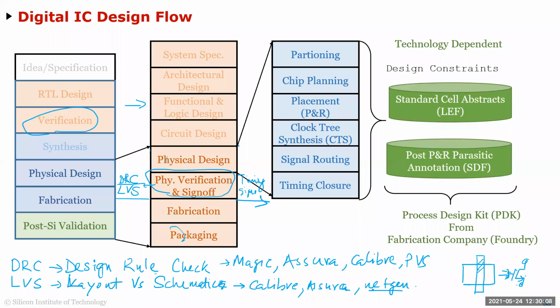So what the tools do is take this capacitance and convert it into timing data. For example, you have an inverter with a propagation delay of, let's say, 100 picoseconds, 0.1 nanosecond. You do this gate-level synthesis and it'll estimate that probably the capacitance is 1 femtofarad.